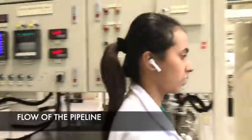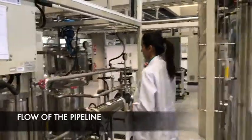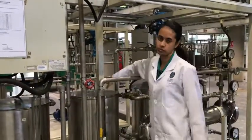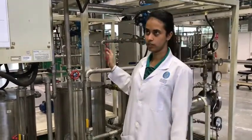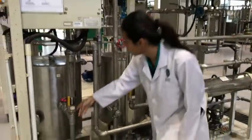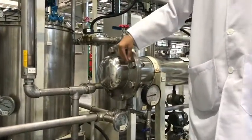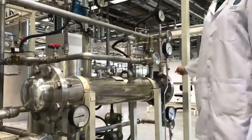And now I'll be talking about the flow of our experiment. So first of all, the hot water travels from the hot tank and the cold water travels from the cold tank, and this is the product tank where the cold water goes into after it has been heated up to its set point. So the cold water flows from here and enters the shell and tube heat exchanger. The cold water enters at the shell side, and the hot water enters at the tube side.